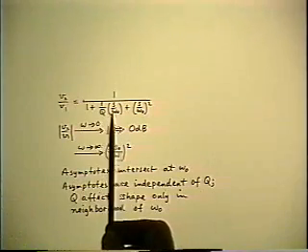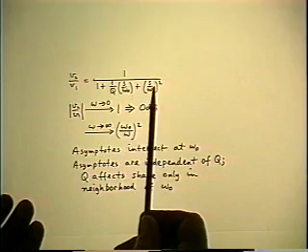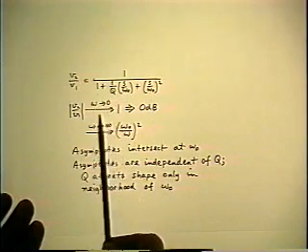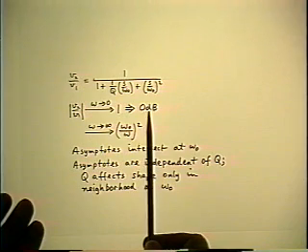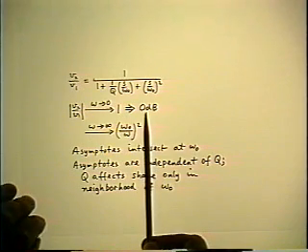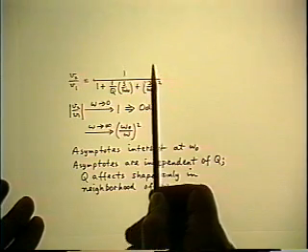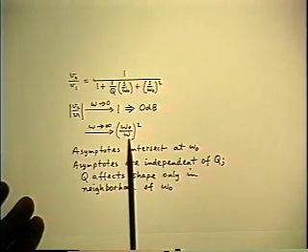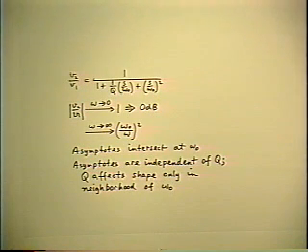The way to start, again, is to look at zero and infinite frequency asymptotes. If s goes to 0, the function goes to 1, so we have a 0 dB flat gain at 0 frequency. Go to the other extreme, as the frequency goes to infinity, it becomes a 1 over omega squared function. So that is a double negative slope, minus 40 dB per decade.